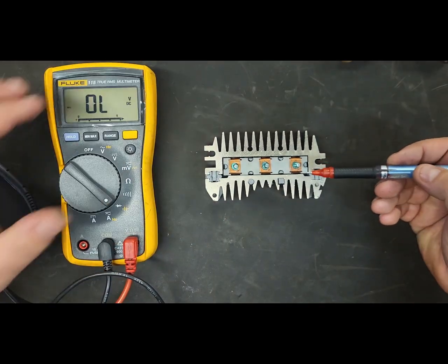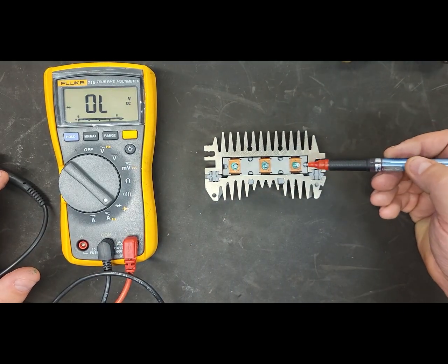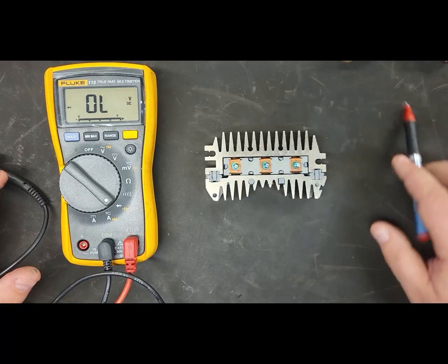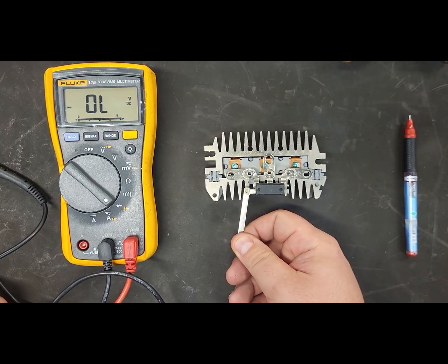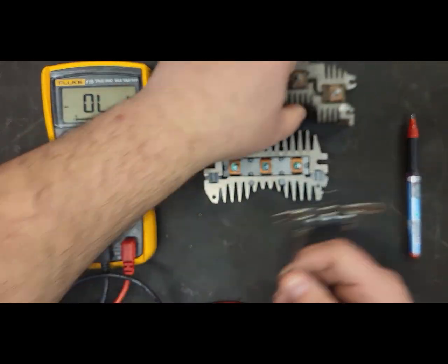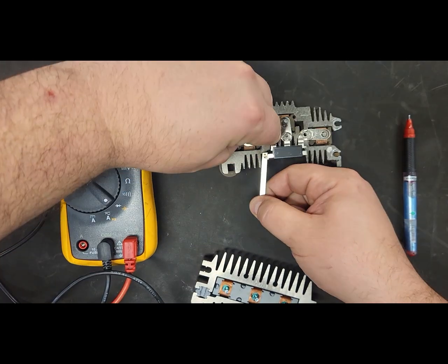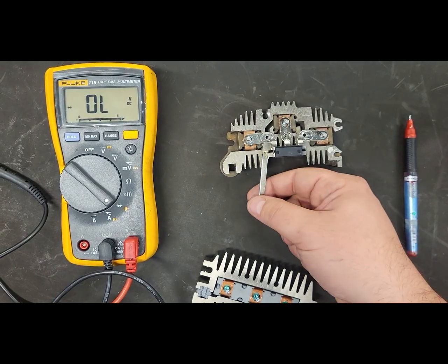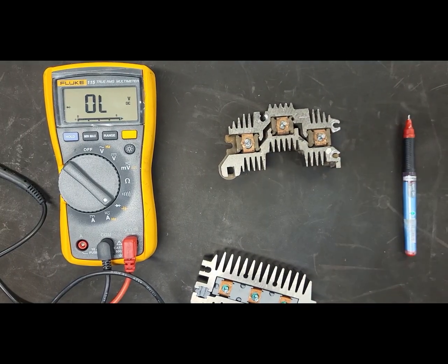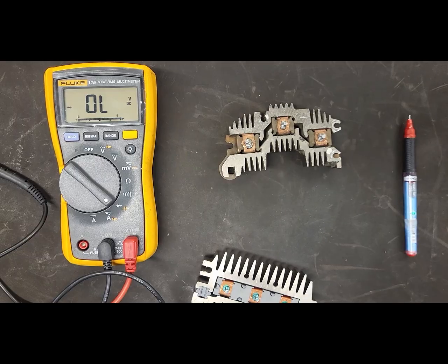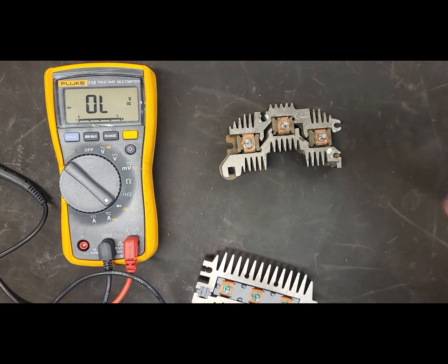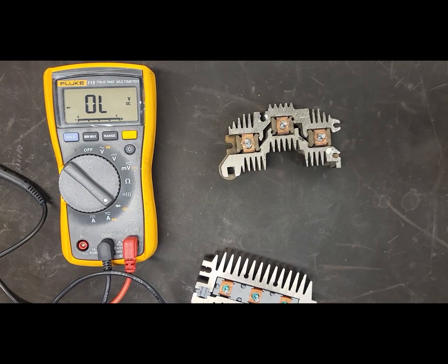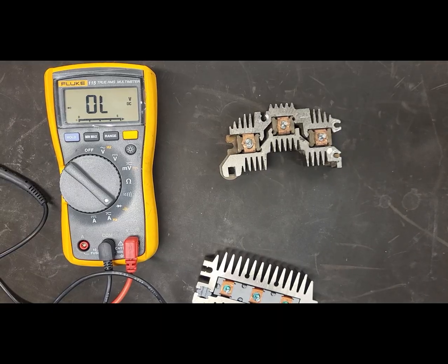2 of those diodes are going to be correlated to each output terminal of our stator, which will also be feeding my diode trio. Now this is the wrong diode trio for the rectifier. That should mate up nicely if I get one of my other diode bridges there. That fits on there quite nicely. That's the diode trio that supplies my input circuit from my output circuit. My stator is going to be feeding through that diode trio, a set of 3 diodes, and supplying my voltage regulator and my slip rings on my rotor to feed current to my input circuit.